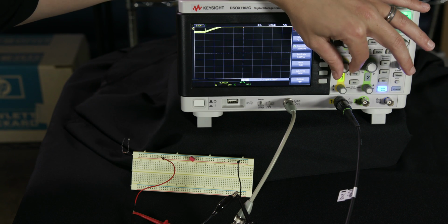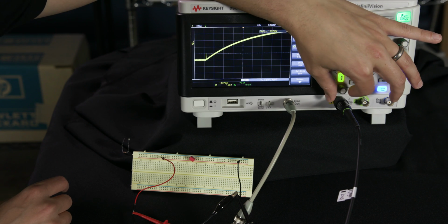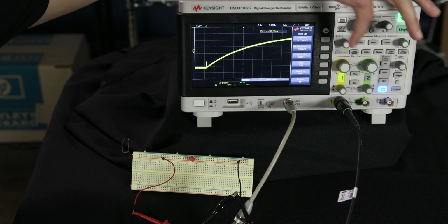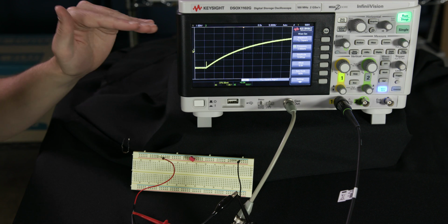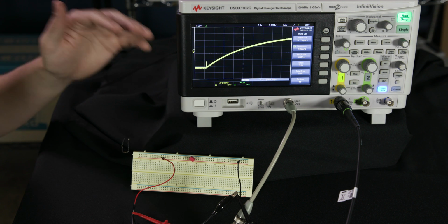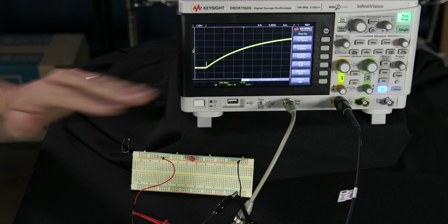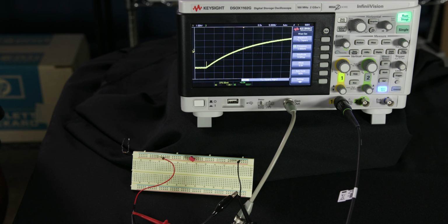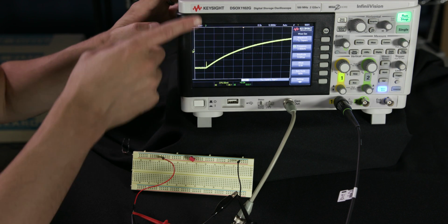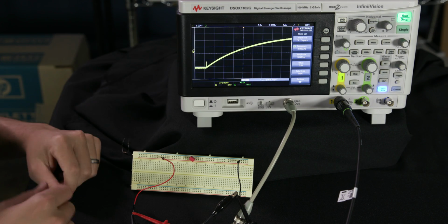Now you might ask, why is the spike only, it looks about a volt tall instead of the WaveGen, which is a 5 volt peak-to-peak signal. So I'm only getting 20% of my maximum height. That's because the scope is not ideal and the WaveGen is not an ideal system. So if I had an ideal edge, this might go higher, but the scope's bandwidth is not going to be fast enough to measure the pulse all the way to the top and all the way to the bottom of that 5 volts.